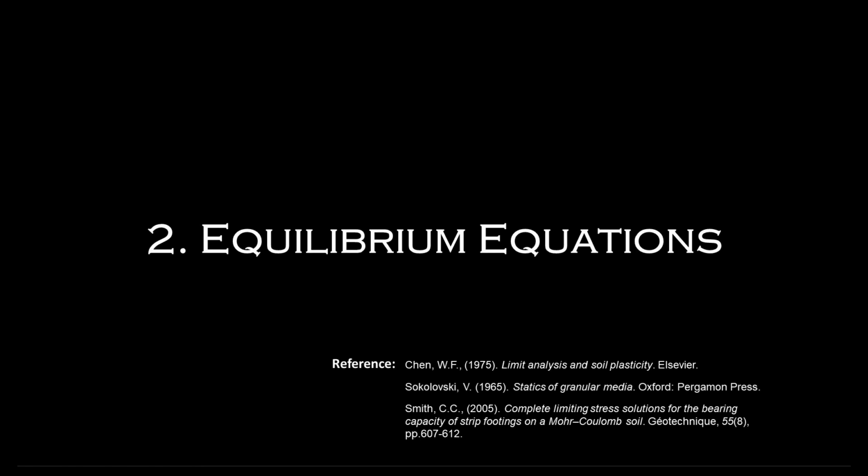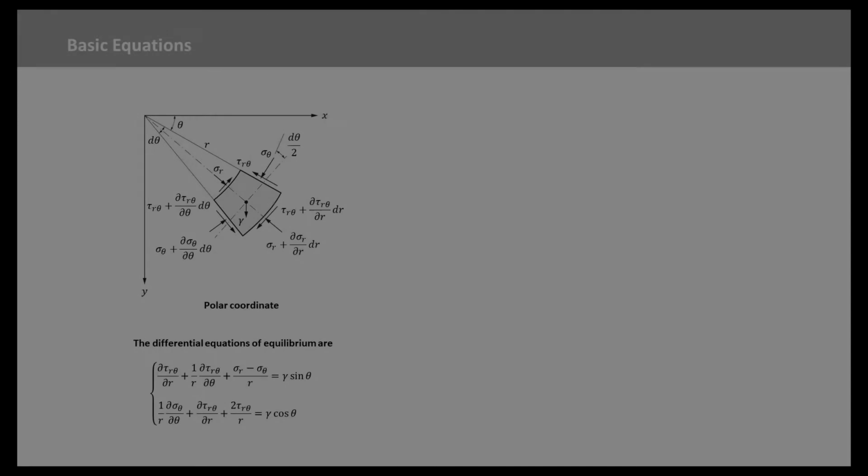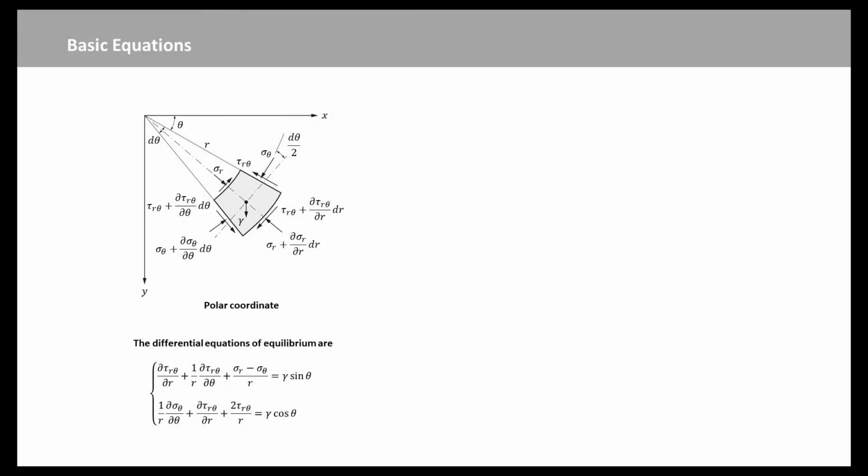For the sake of simplicity, the soil is assumed to be an ideally granular medium. The shearing resistance of the soil is phi. We start with equations of limiting plane equilibrium of a wedge. The properties of an ideally granular medium make it possible to obtain solutions to many problems more easily if we consider the limiting equilibrium of a wedge. It will be shown that the solutions to all these problems can be obtained in closed form.